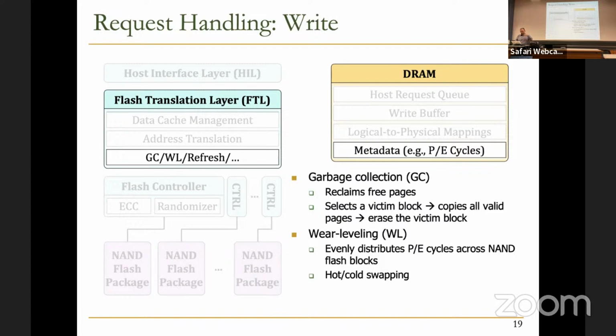at the high level, most of the time they need to swap hot and cold blocks. If there is a block which is hot, meaning that you write to that block a lot, and there are some blocks that are cold, meaning that you haven't written to them much, you can just swap them, basically. And that's quite easy with SSD implementation, because you already have this mapping.